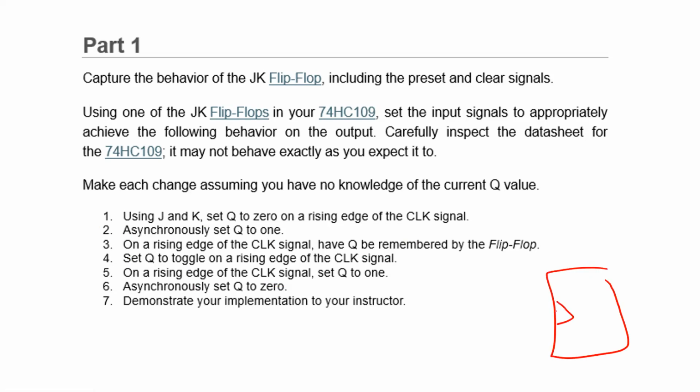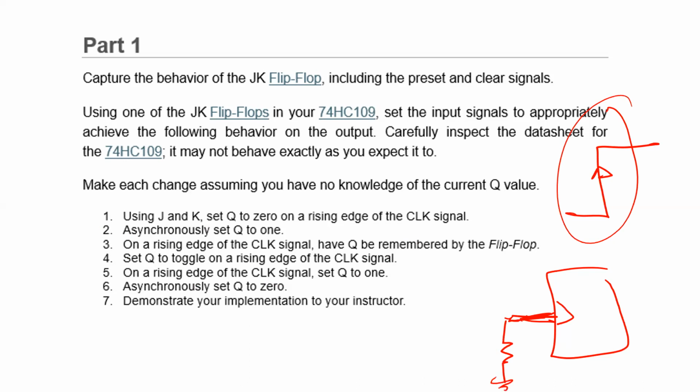So the way you can do it, because this is a positive edge, is this way. It has to be this way. Is that okay? So I can connect this one, for example. I can use a resistor this way, connect it to ground this way. That means all the time it is 0. Okay. And then I'm going to make a switch this way and connect it to 5 volts. Is that okay? So normally it is 0, and once I close the switch, I'm going to make it 1. This way, I'm inputting a clock manually.